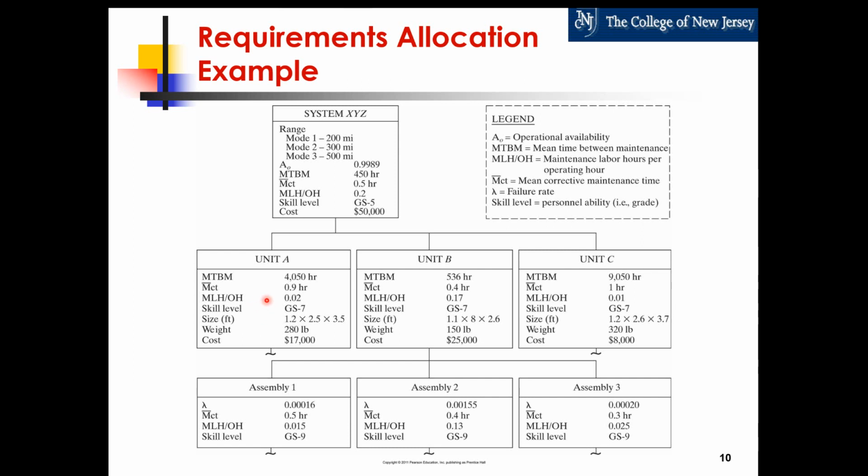And what you can find is that, as I said, if you have certain availability and reliability requirements of the system, the subsystems have to have a much higher reliability. So when you put them together, they achieve that overall reliability level, because if one thing fails, then the whole thing fails. So it's important to recognize that you can do this type of allocation and budgeting once you understand the functional allocation and the composition of the system.